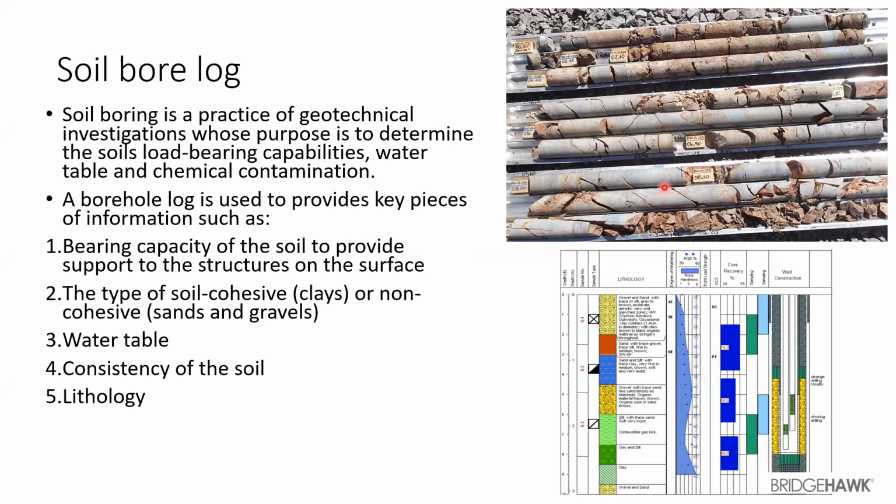So on the right hand side, you see a photo, which is basically a bore log, practical. And the one below is the bore log report. This will give us an idea about the strata below the pier. Based on this, you are going to set the safe bearing capacity, modulus of subgrade reaction, and all the constants that you are going to need. You'll be finding them from the lithology.